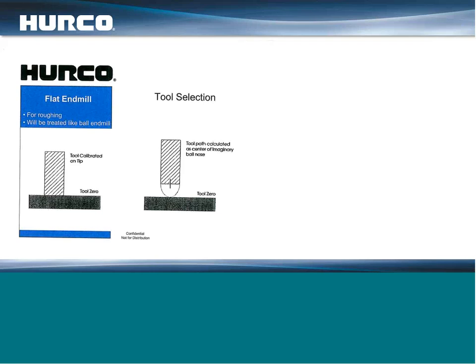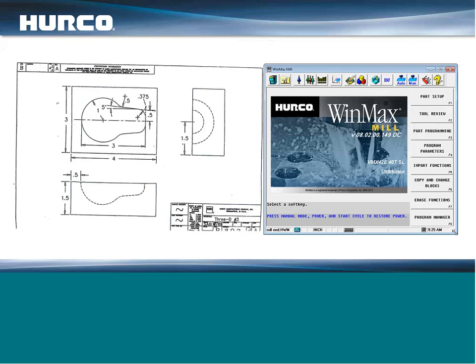If the top of your part is Z0, that retract clearance can be pretty much anything, because it's going to go from your Z start. Now, if the bottom of your part was Z0, however thick your block is, you want to make sure that your retract clearance is at least larger than that. But there's no special consideration than any other program? No, it works exactly the same. It's just that that's the only parameter it's going to look at when in a 3D mold block. Okay. Everybody okay?